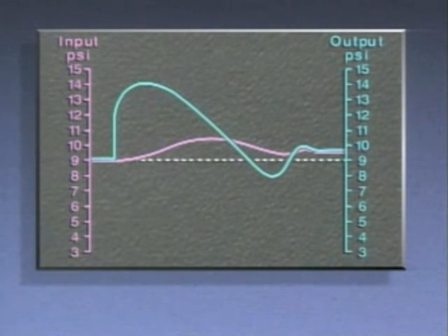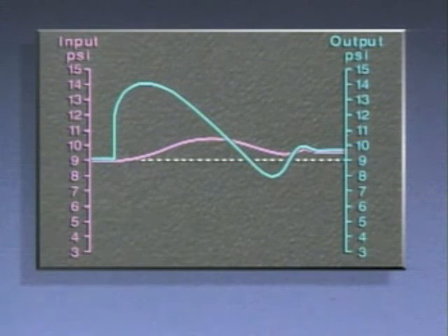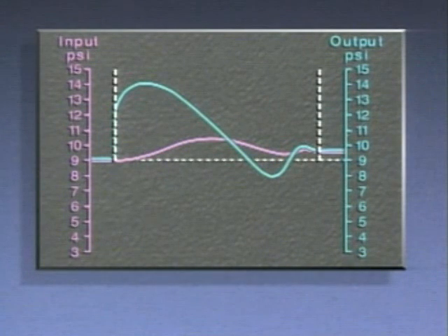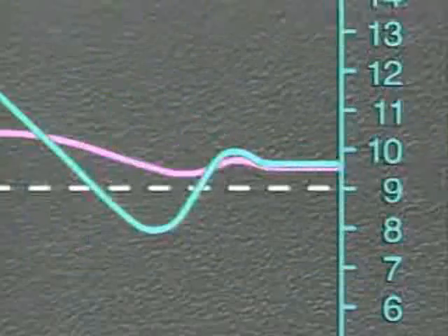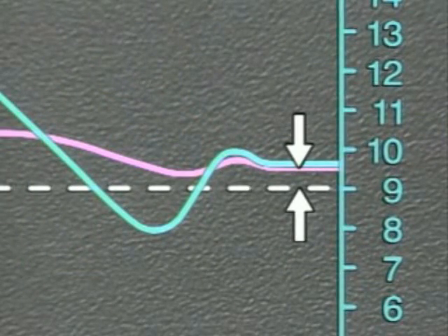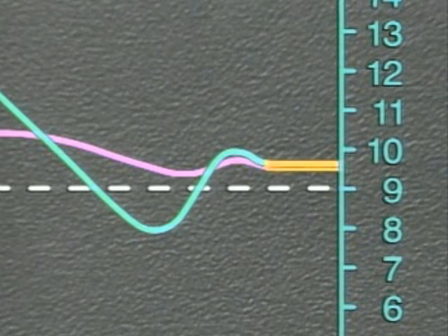Then, a combination of rate control and proportional control stops the water level from changing and brings it down almost to set point. However, because rate control responds only during changes in the input, and because proportional control only provides a proportional output, there may be some offset in the process variable. In other words, as long as the level is at steady state, even with offset, the rate controller will not provide a correcting output.